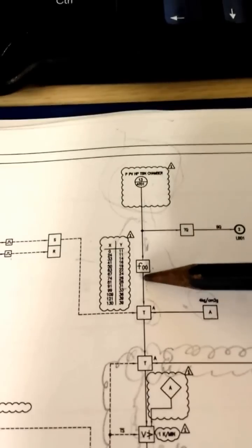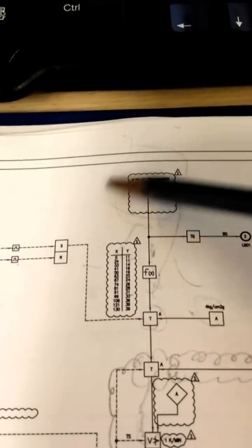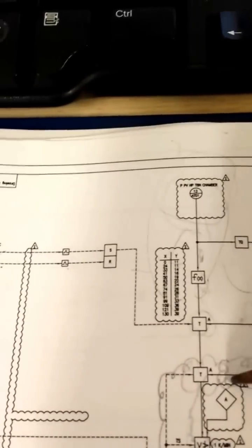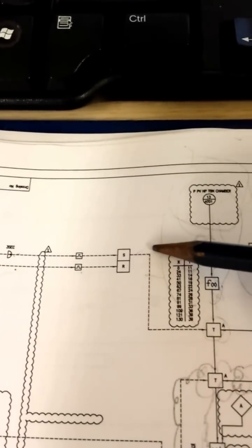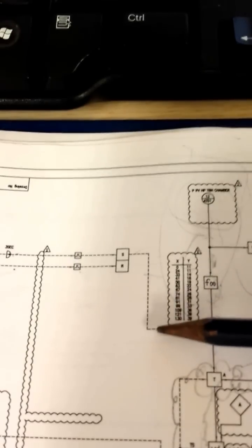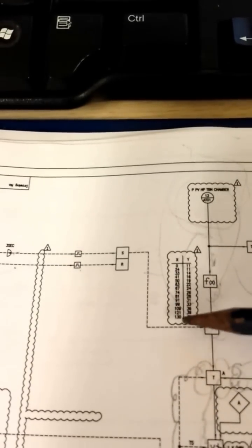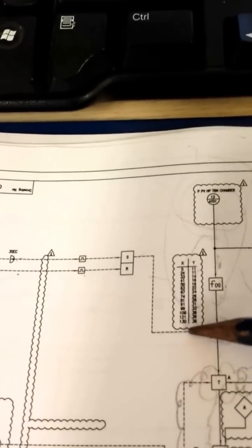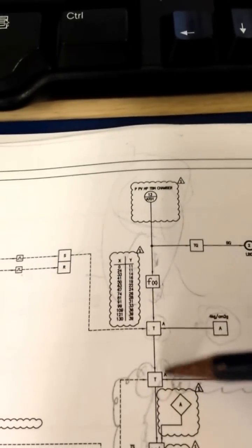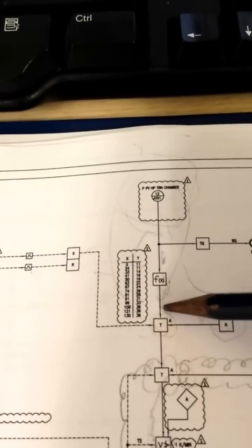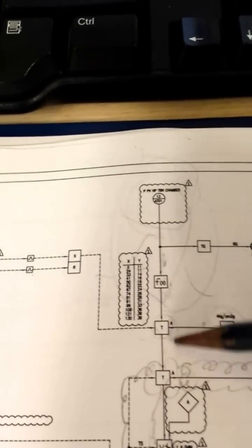The 39 value is coming from this line. This is the actual value. To determine which particular input will become the output is this. We can see the broken line. That means it is logic signal 0 and 1. So if logic 1, the fixed value of 4 will become the output. If logic 0, the process value will become the output, and consequently become the set point.